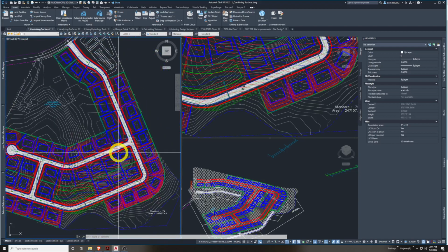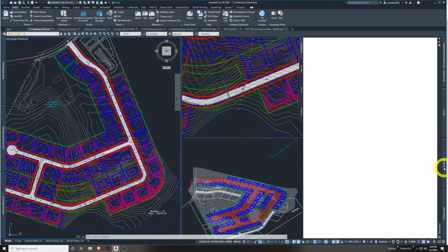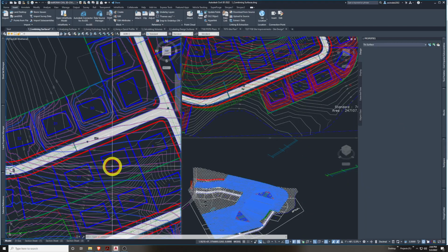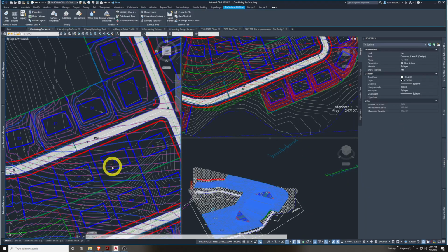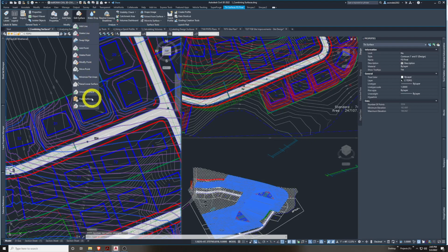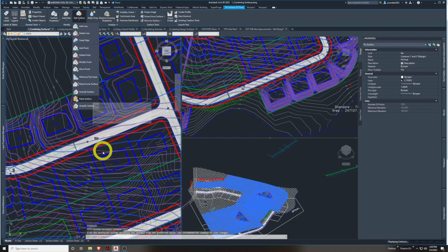So to go back to there, we'll go a different route instead of through tool space. Let's click on the noun, the object, and we'll go through the ribbon this time. So as I did before, I selected the surface, which is in blue, contextual ribbon with options for it. And it's the one we just made. You can see it there in the contextual ribbon as well. We'll go this time to edit surface this way, and we'll access it through the ribbon. And same options, but we're going to keep going with the same one, paste surface again.